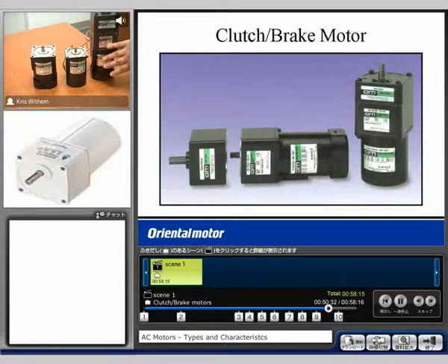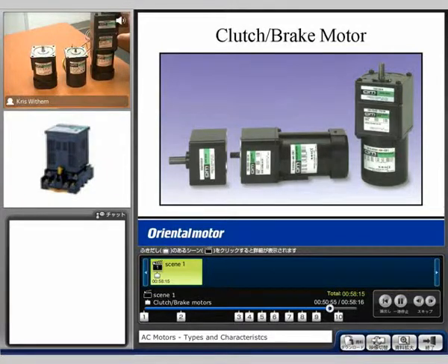This is a quality issue. What we do is each time we assemble or make a clutch brake series, we test and assemble it mated to the motor. This ensures that throughout all the testing processes, this assembly was guaranteed to work for you or for your customers. The gearheads are interchangeable. We can change different types of gearing on here. This specific one has a 9-to-1 gear ratio. We could change this to a 15-to-1 or a 20-to-1, and all you would have to purchase would be the gearhead itself.